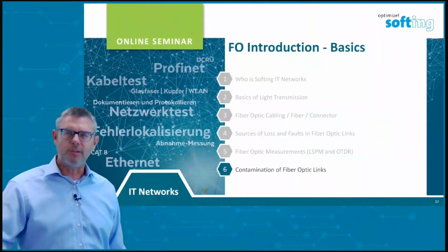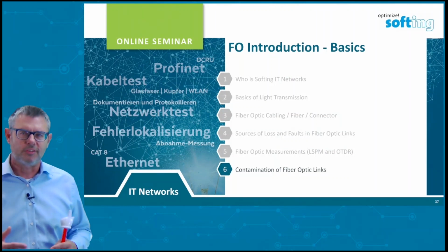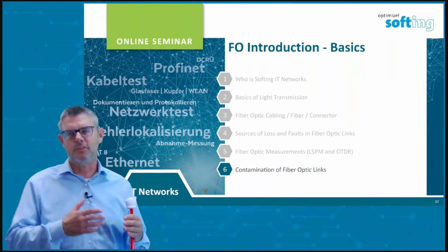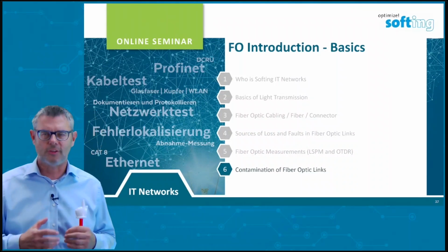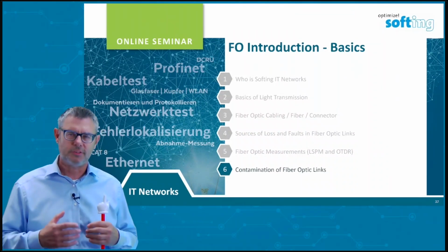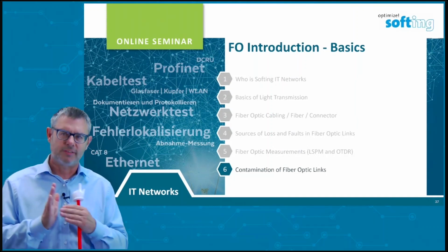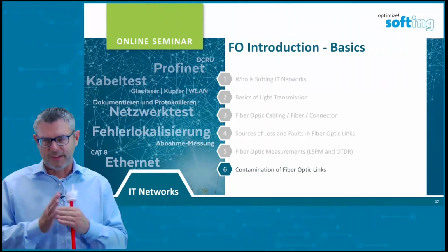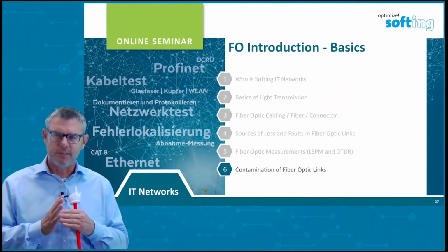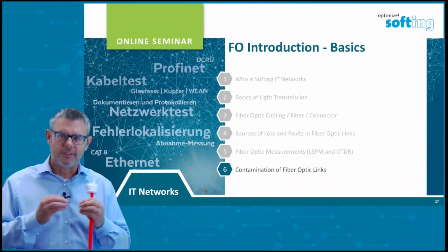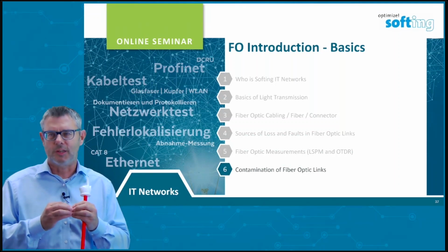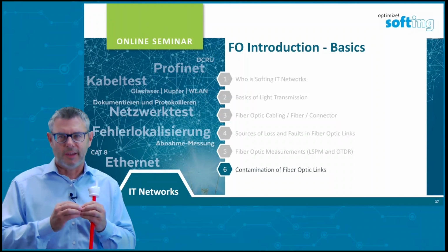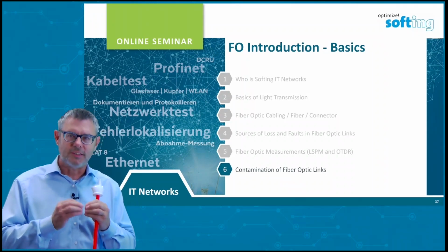Now, the point I usually mention in presentations always before I talk about measurements, because it's so important: you have to do it each time before you make a connection on a fiber optic cable. You have to see whether the connector end face is clean, not defective, not broken, and the glass is still completely intact. Because if you connect dirty connectors together, you might get real trouble in getting light traveling through this connection. So you have to make sure that every connector is really clean.